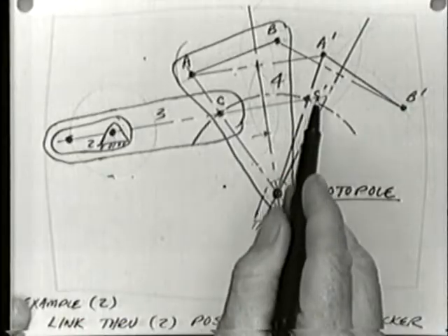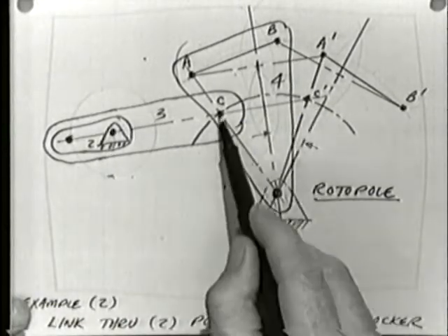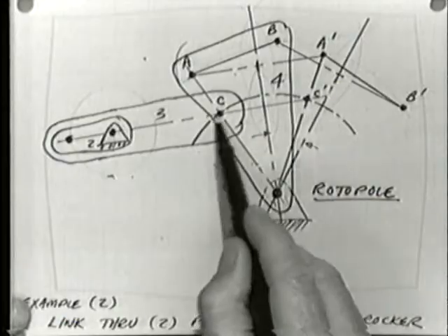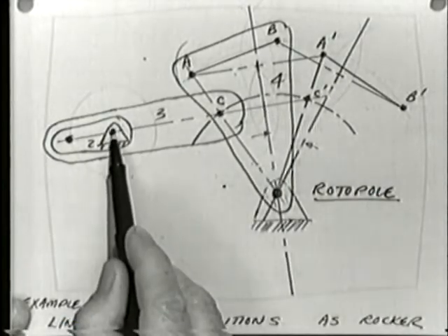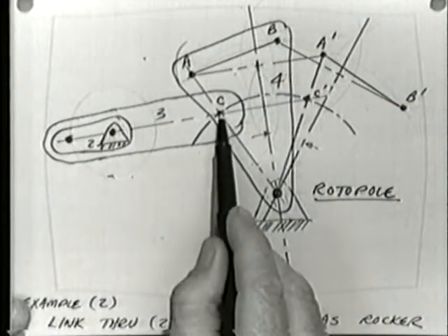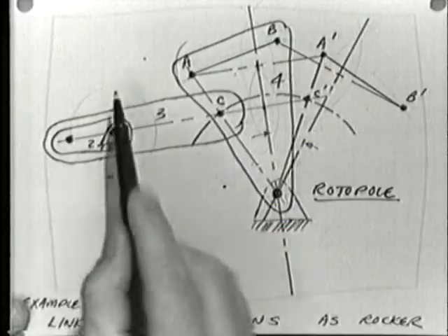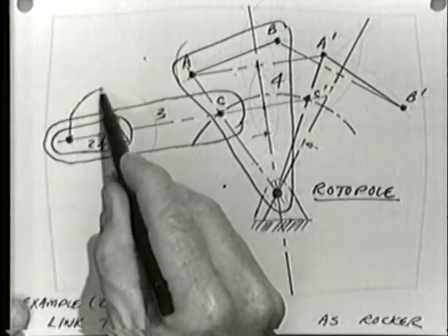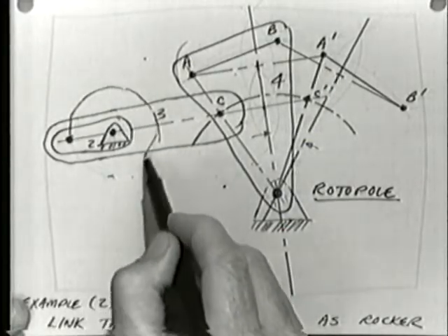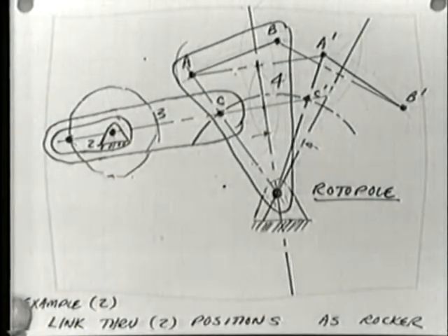Then we went back to the Grashof non-quick return synthesis procedure, picked an arbitrary point C, found out where it ended up, cut that distance in half, picked a point somewhat at random, found the circle at that radius about this center, which is the track of that pivot, and then connected the dots, coupler and crank.